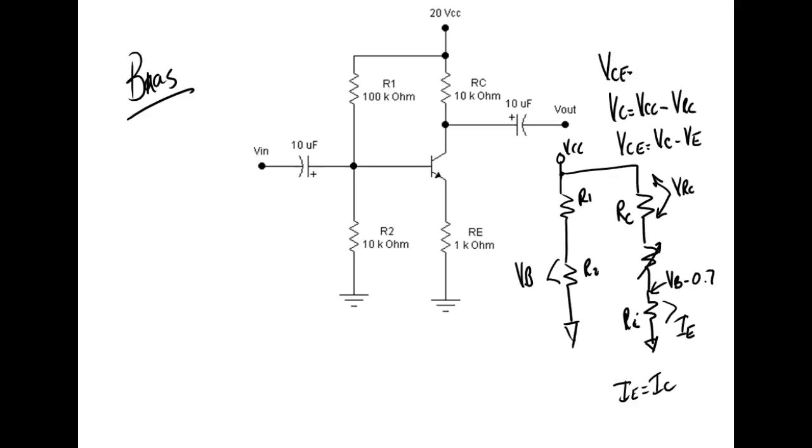These are test questions. What is bias? This is a DC voltage we apply to a semiconductor device to set its operating characteristics or parameters. That's what we're doing. So what we just did is we biased this transistor in the active region. And now it's biased in the active region. Now it can amplify, right?